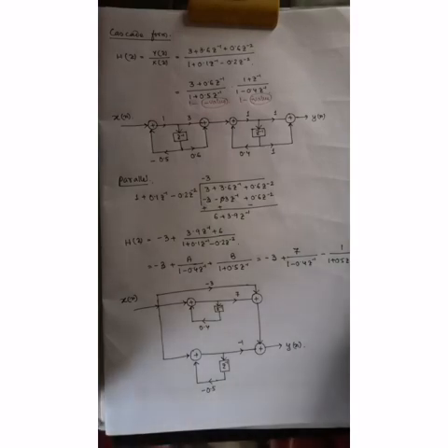Another part is the FIR, that is, the non-recursive realization, where the output sample y(n) is a function of only the past and present input. That is for the FIR filter. So that's all for the IIR. In the next class we will discuss the FIR filter, how to design it using the rectangular window, Hamming window, Hanning window, and Kaiser window. We will discuss that subsequently in the next class.